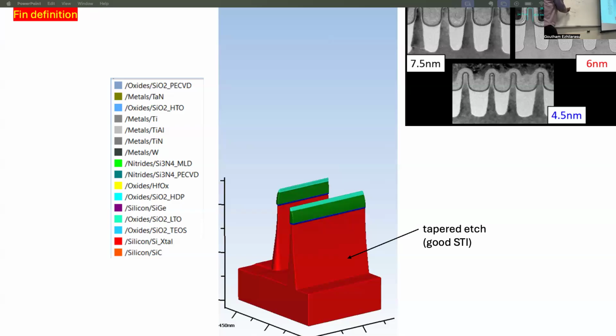And what it does is control the diffusion. Then you can put N+ poly, some highly doped polysilicon. When you anneal this, the N dopants migrate into the silicon and end up creating a well, which is N-type here. Then you can remove the poly, okay? So that's one way, using diffusion to dope the silicon, but you can also use ion implantation to dope the silicon, okay? So that's why I'm saying this is one way to do it, okay?